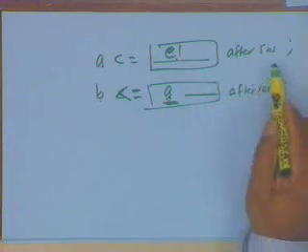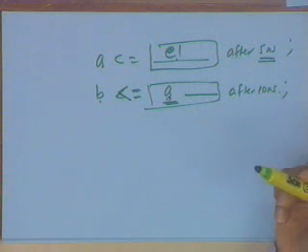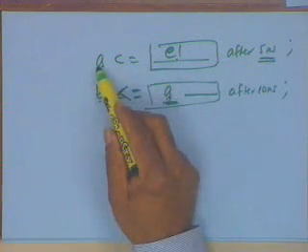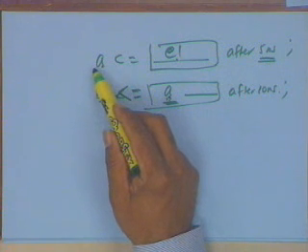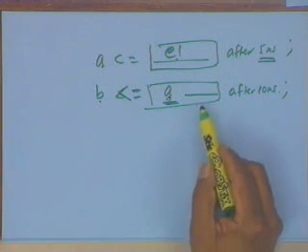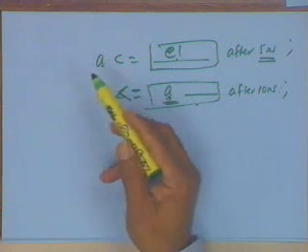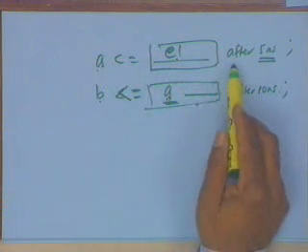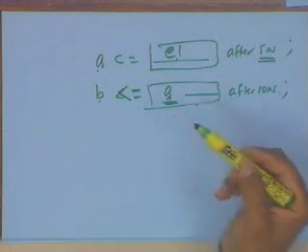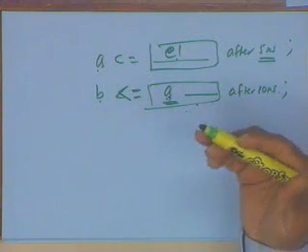But this assignment will be valid only after 5 nanoseconds. It will be scheduled to happen after 5 nanoseconds. Now, after 5 nanoseconds, the value of A actually changes from whatever is the present value of A. This will get re-triggered. So the implication is that it will get one value after 10 nanoseconds and it can get another value after 15 nanoseconds, because the value of A changes. If the value of A doesn't change after 5 nanoseconds, then this will not be evaluated. That is the complexity which comes in concurrent assignments.